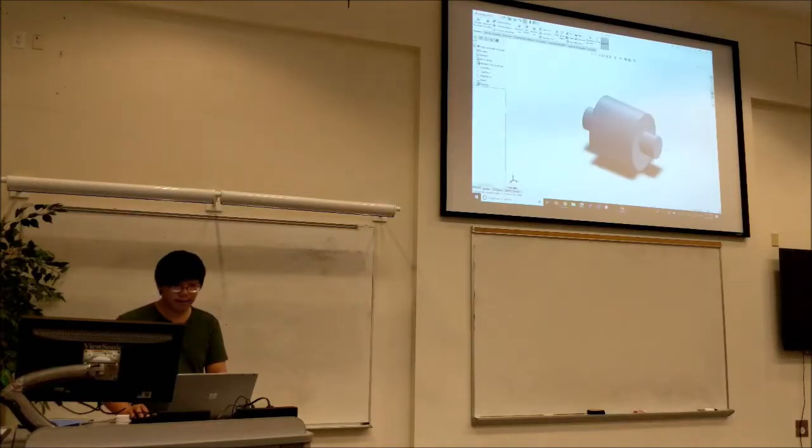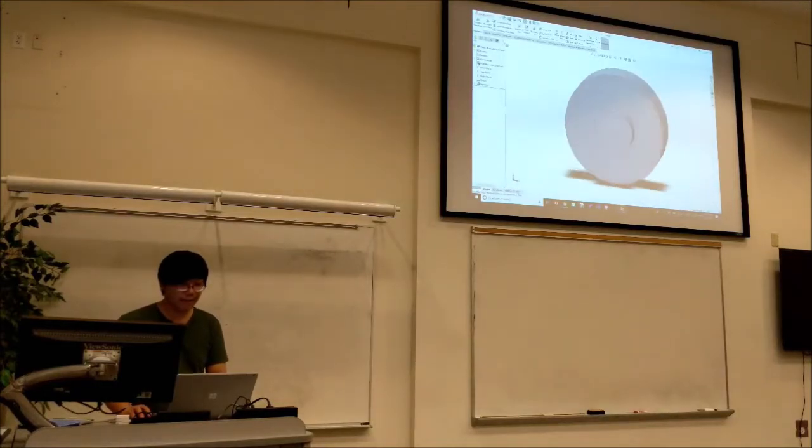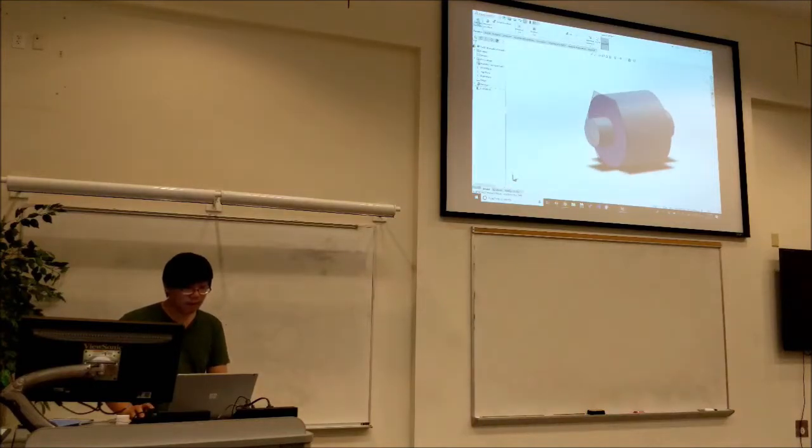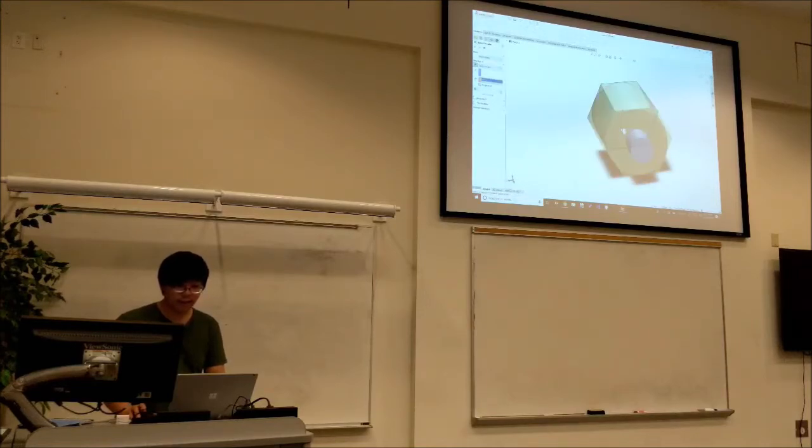We have it. This is obviously not the shaft we want to drive that gear, but if we go here and make this a hex, then we can make this co-radial to this. What this does is it ties this entire shaft back to the first sketch. So if we make this horizontal, and then we can do up to surface, and then select this surface.